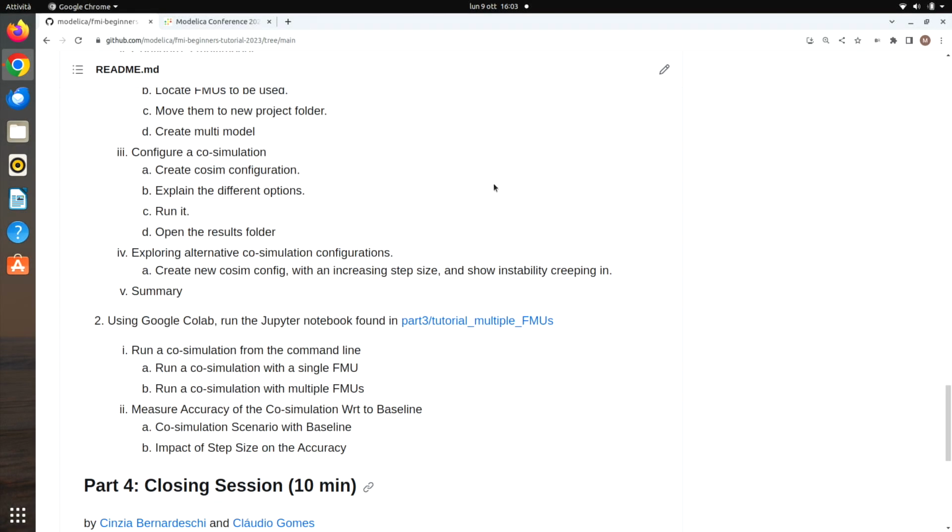So to be clear, all these FMUs are being run in the same process. These experiments are totally independent of whether you want to parallelize, and they are computed sequentially. There is wall-clock time and there is simulation time. In simulation time, they're computed in parallel, in lockstep. But on the computer, they're literally in sequence. Thanks, that's a good confusion. But this is up to the tool, so there are other tools that could even distribute remotely or whatever.